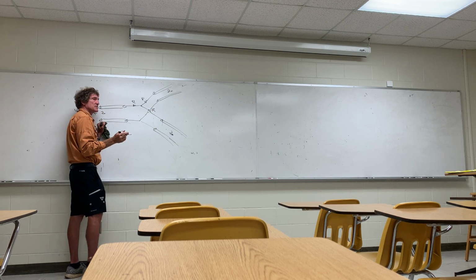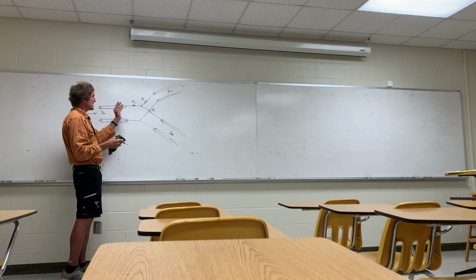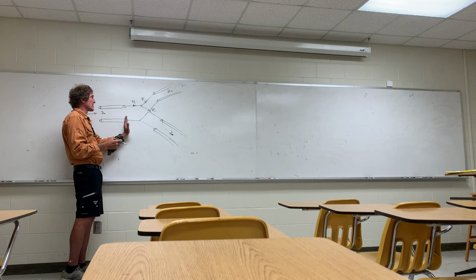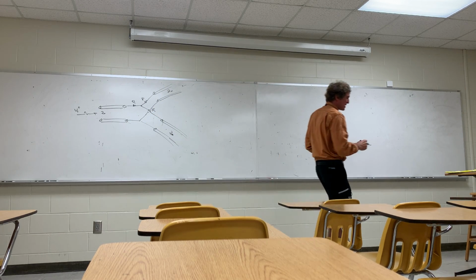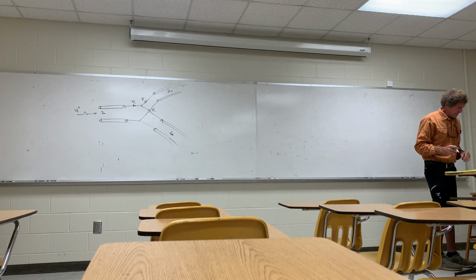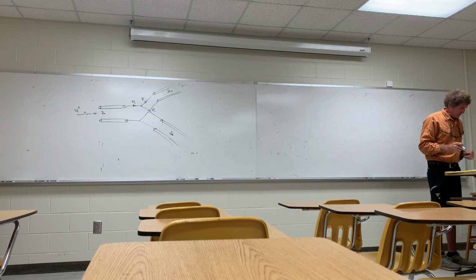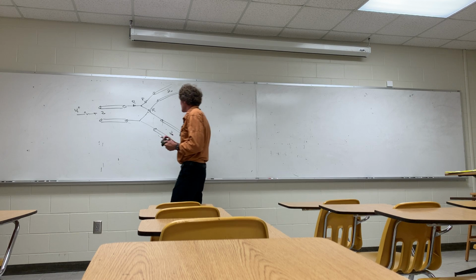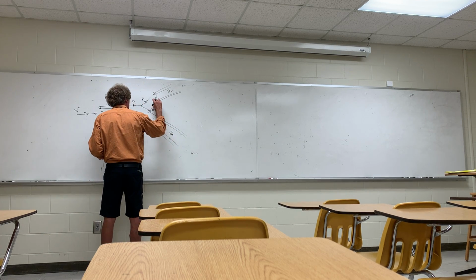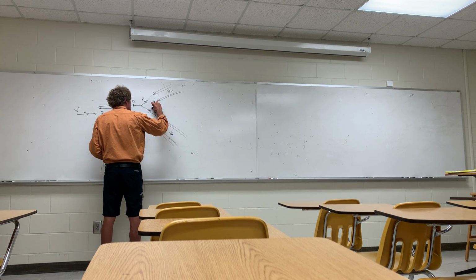Now the value of these resistances is calculated so that the input impedance right here will be Z0. Now the drawing of this is in the book, it's at the bottom of page 570 if you look at it. So let me go through this with you. We're going to talk about how to get these values. You don't even need that line there, but the only thing you need to do is understand there's three values of resistance.